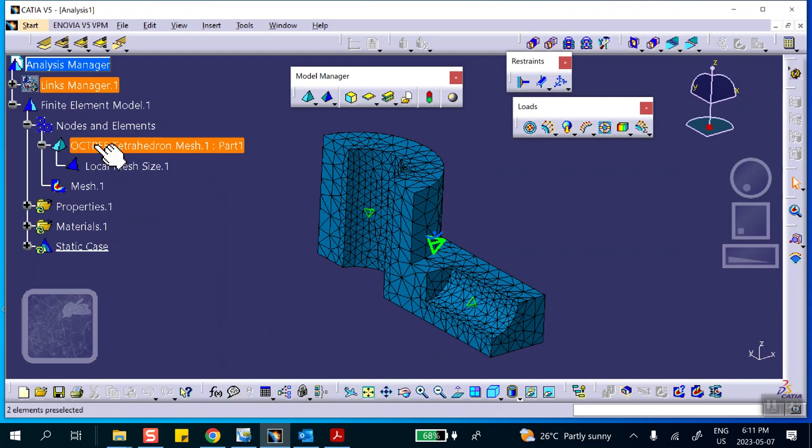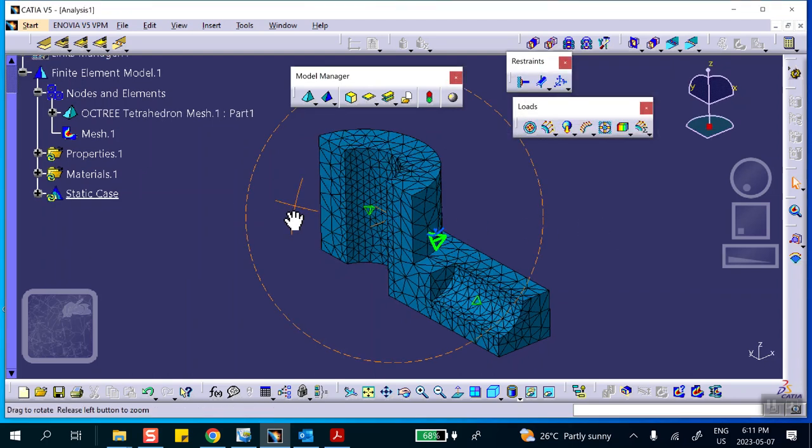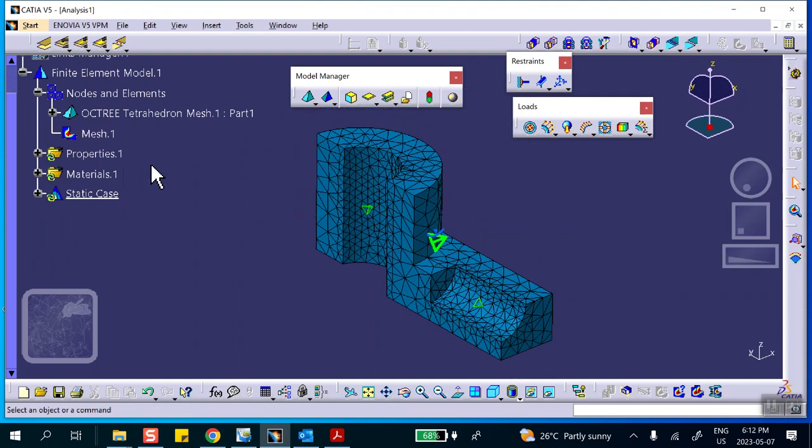Yeah. Now, by the way, when I started, I had the choice between linear or parabolic element. Linear is faster but less accurate. Parabolic is slower, obviously, and more accurate. But on the test, unless we give you any instructions, use linear with default element size. Okay, and if we told you to do a local mesh refinement, please by all means do it.